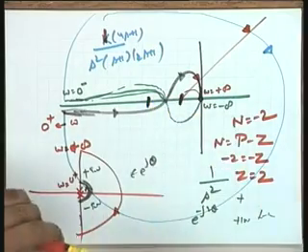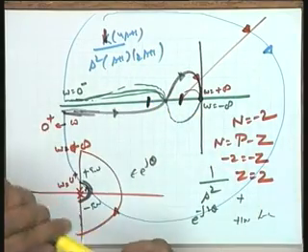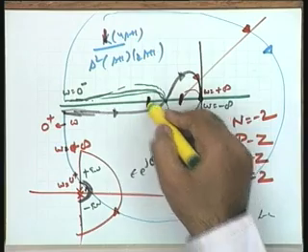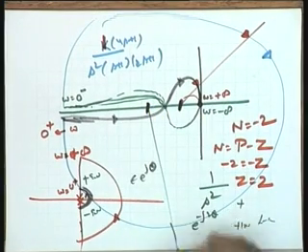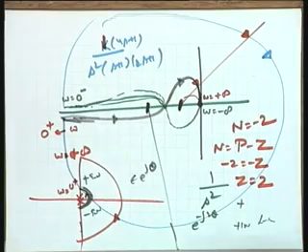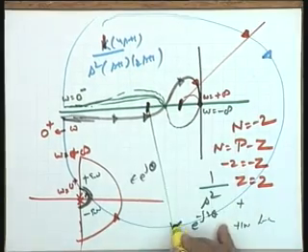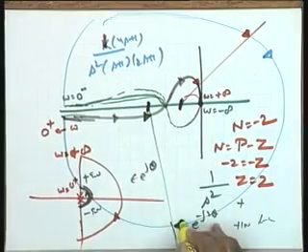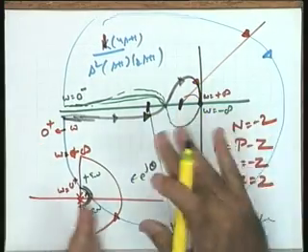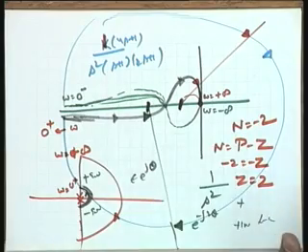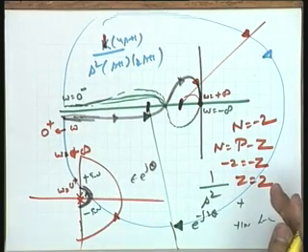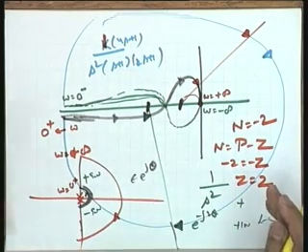Consider that your magnitude k is such that the point lies here. Come on, please help me. Just draw any line. N is 0. You see in this case, as you have very clearly identified, N is 0, because of the net encirclements. One is in this direction, the other is in this direction. Physically it is clear that the point -1 is not encircled. Even if you draw the line, the criterion meets the requirement. N is equal to 0, P is already equal to 0, therefore Z is equal to 0, and hence the system under consideration is stable.